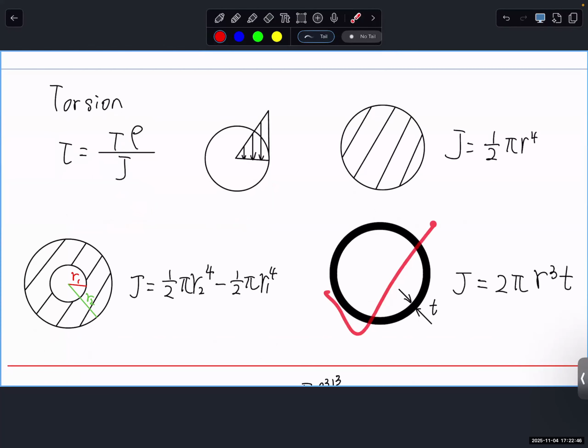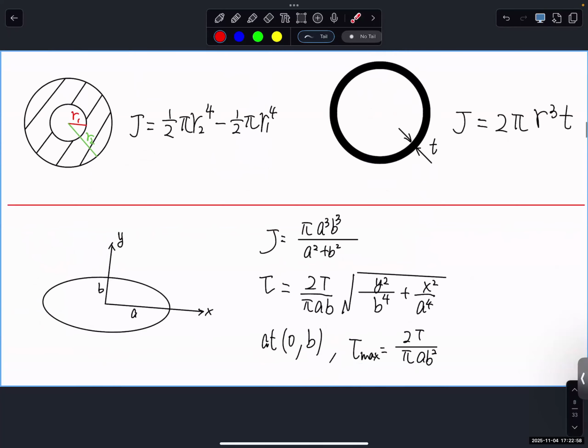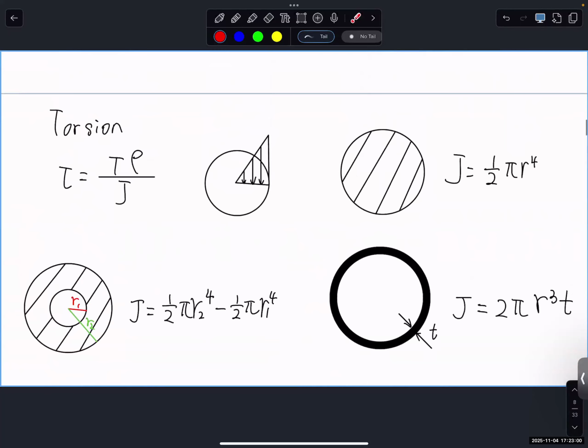So that's why in a lot of real life applications, when the major load is torsion, we normally put a thin wall. Material in the middle actually does not matter that much because the stress is just so low. So you put thin wall on the outside, where it has maximum shear stress. For a material, whether it will fail or not, it's all because of stress.